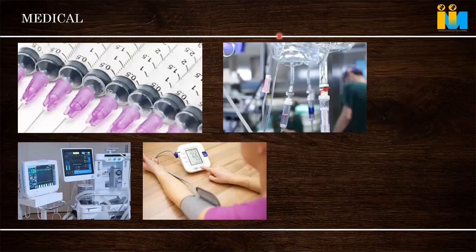So these are some medical applications. We come across a lot of medical applications. Majorly the regulation is about biocompatibility. As I told you, there are some rare applications where the implant happens inside the body, so a lot of regulations are there, and very few raw material makers take that risk. Syringes and all are made of polypropylene because they have to be sterilized. Since blood is going to be in contact, we use biocompatible material. Otherwise the pouch is made of biocompatible PVC, and PVC tubes are used.